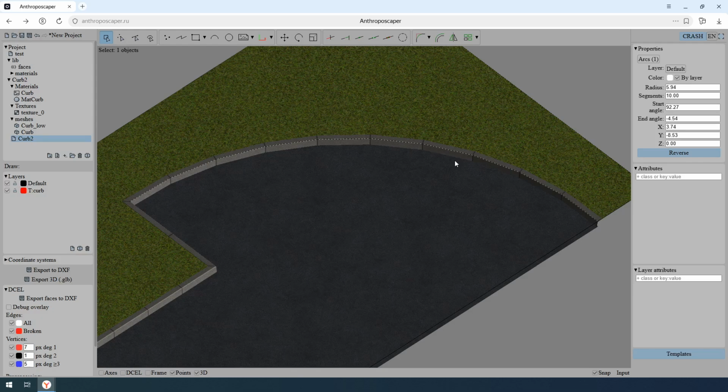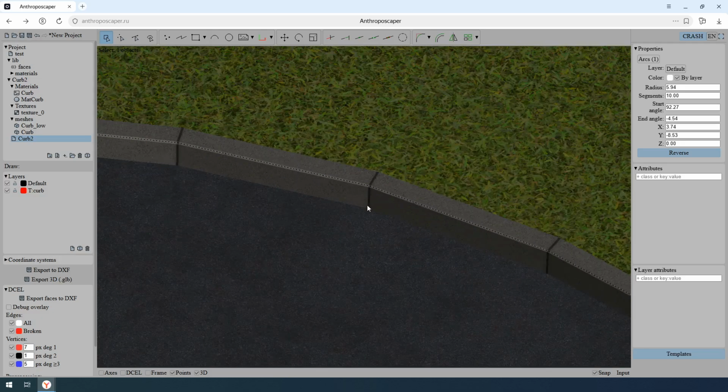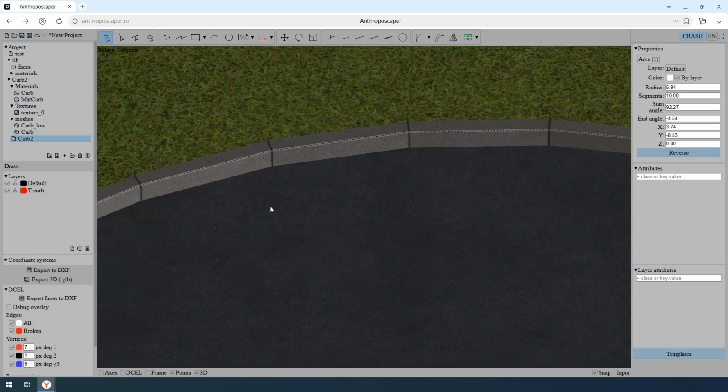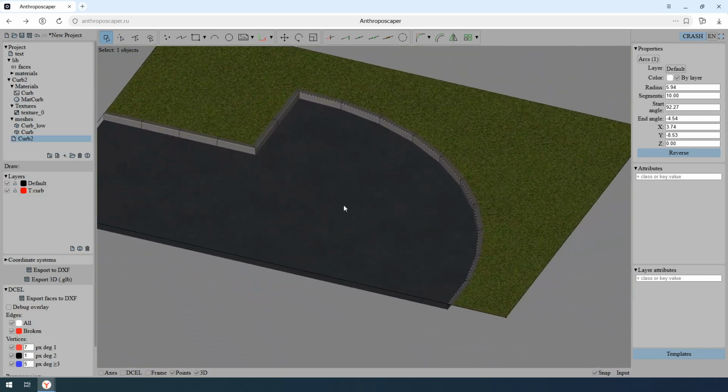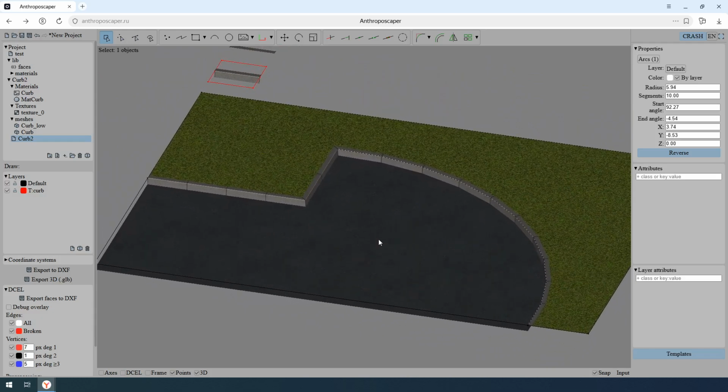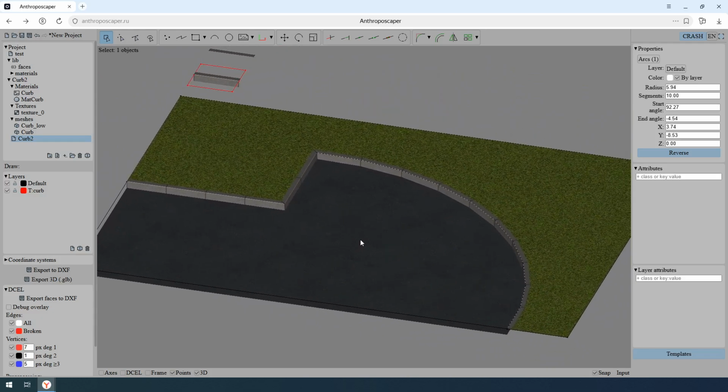And now everything lines up. The segment length equals the curb length. So each straight segment of the arc gets exactly one copy. The curbs sit along the chord, 1 to 1, with no stretching and no bends inside a copy. The arc's subdivision and the template's layout are now in sync.